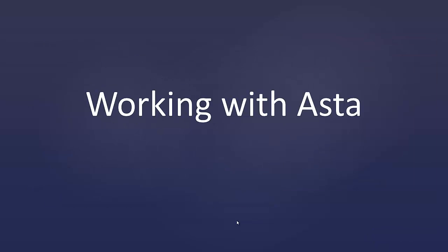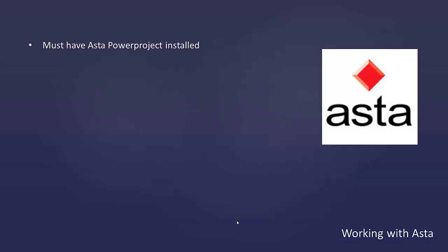So that's P6. Moving on to Asta Power Project, just a few quick notes on that. Like P6, you must have Asta installed on your computer, even though it is a file-based system, not a database. You will need a copy of the program on your computer in order to import and synchronize with that program. And that's just because of the way Synchro connects and reads the data from them.